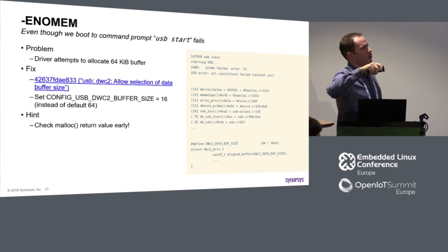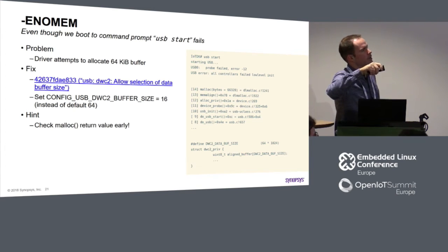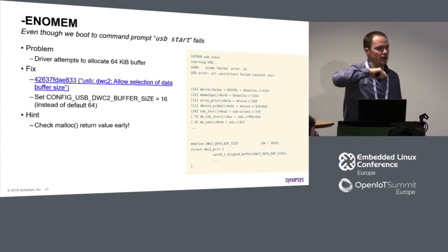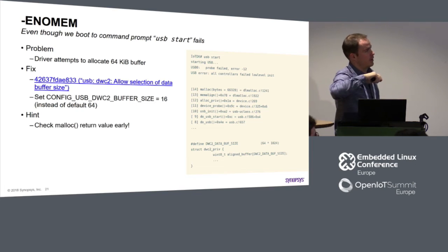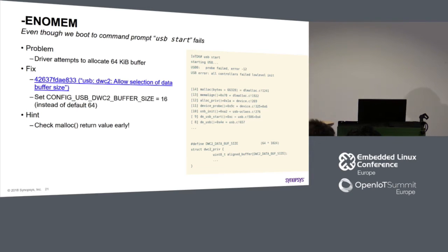And what happens? Well, it says error -12. Like what? Okay. Error -12 is essentially ENOMEM, which means we don't have enough memory during allocation in our heap area. And what helps here, if we take a look at our backtrace, we may see a couple of interesting things. So we start USB initialization, then we do device probe, and then we do allocate priv, which